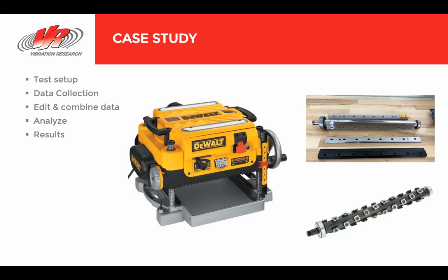So that's a basic introduction to octave analysis. And overall, this process is relatively simple. Open a time waveform in ObserVIEW, generate the octave analysis graph, and then select the time range that you want to plot that data for. It's as simple as that. There are characteristics and things that we can modify that make it a bit more complex when you start talking about integration time and A weighting, C weighting, different filter shapes, etc. But overall, the general parameters are very simple to use and very easy to understand.